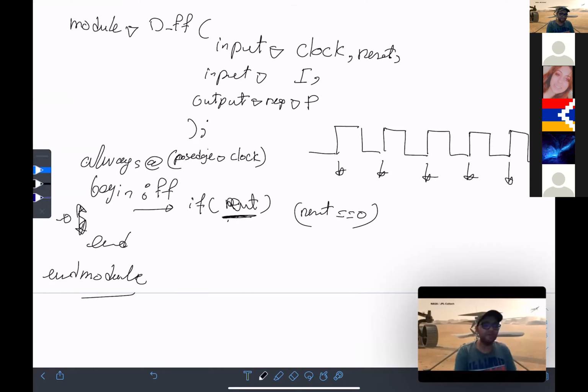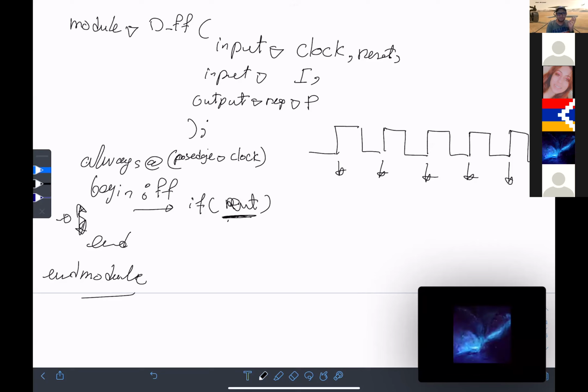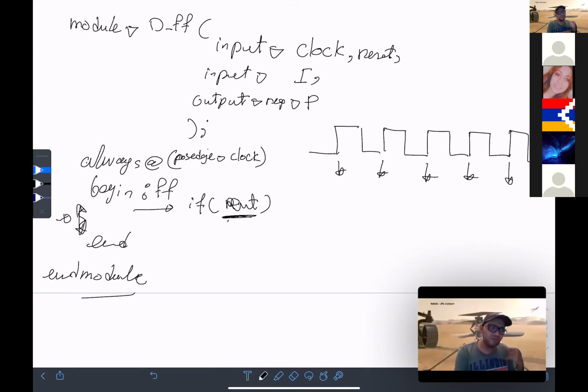You will find it there. Okay, so look, it's going to be reset equal 0 if you want to monitor what will happen when the reset is equal 0. But for us, let's make it reset is equal 1. So you just make it like that, okay? Then, normally, if you are just testing one line under the if statement, you don't need begin and end. But if you're going to have multiple lines, you need begin and end.